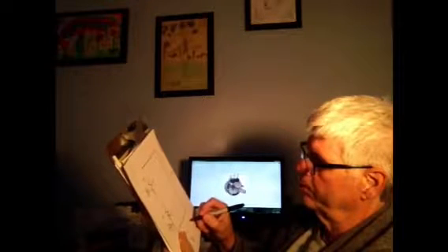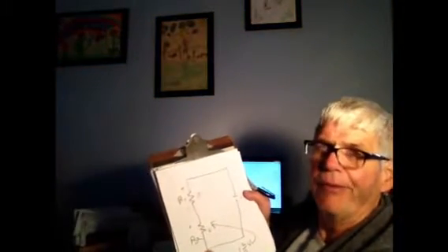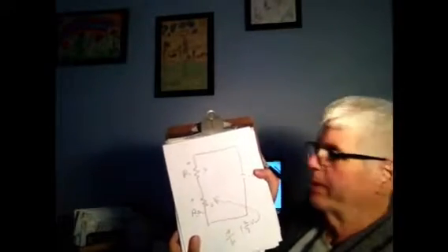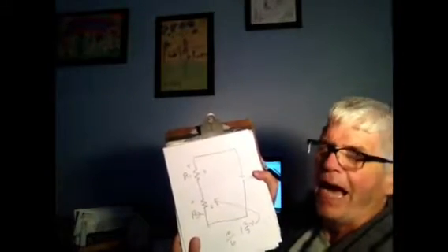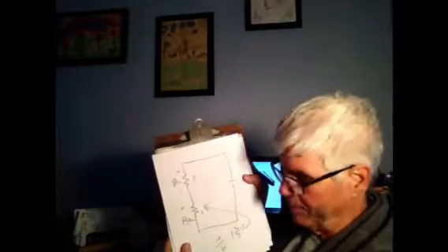Or 10/6, or that's 1 4/6, or 1 2/3. So that'll be 1 2/3 volts. There's a formula for that, okay? Just like everything else in electrical, there's a formula for it. It's called the voltage divider law. I'm not going to give it to you because we're going to keep math to a minimum.